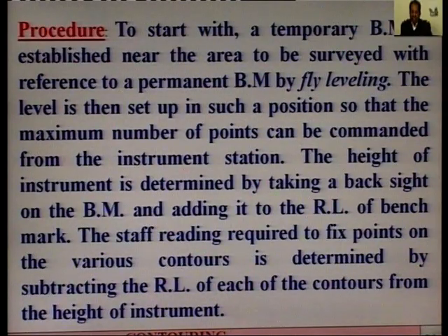The staff reading required to fix points on the various contours is found by subtracting the reduced level of each contour from the height of instrument.